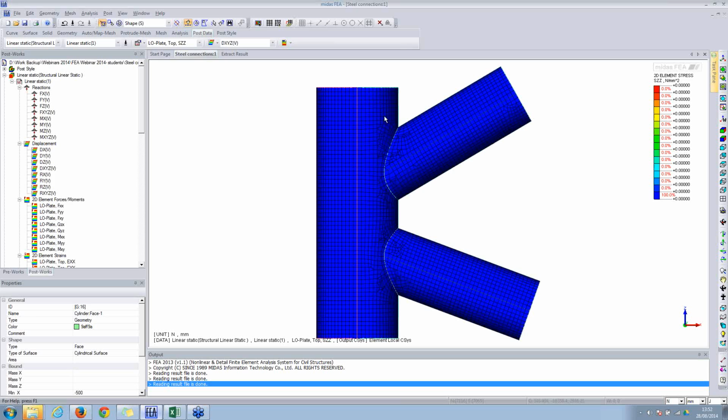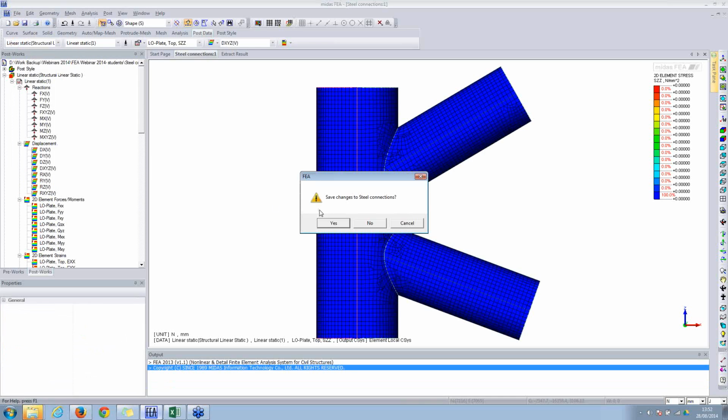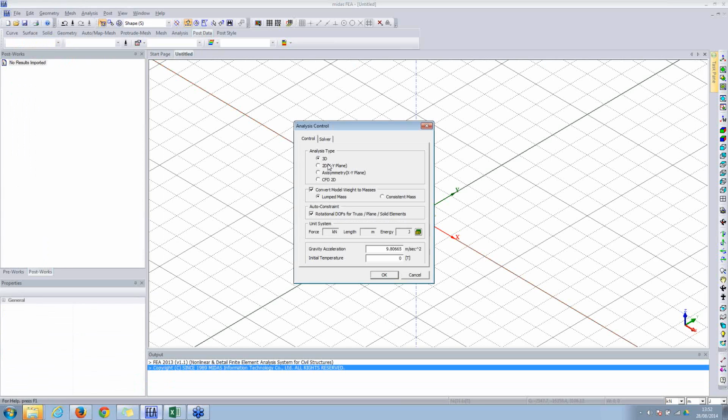Right. So let's now look at the other example for reinforced concrete analysis. We will be doing reinforced concrete analysis for a rectangular beam, simply supported. We'll be applying loads, and we'll be doing a nonlinear analysis and looking at how the crack propagation occurs. We'll be adding reinforcement and then see some of the results. Okay.